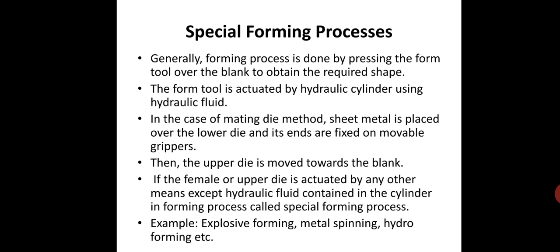Forming process is done by pressing the form tool over the blank to obtain the required shape. We already know what forming is. By using the form tool, we give force to the form tool against a blank to give the required shape. The form tool is activated by hydraulic cylinders using hydraulic fluid.